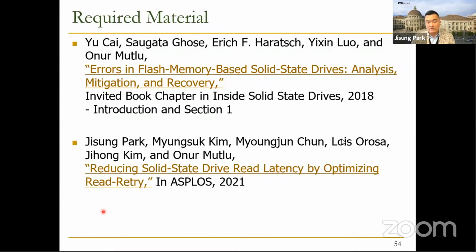In that case, we usually need to read the page to the temporal buffer and update the requested parts, and rewrite the data to another free page, which has been erased before, which means that a single update of very small data incurs one read operation and one new program operation, meaning a significant performance and also lifetime overhead.